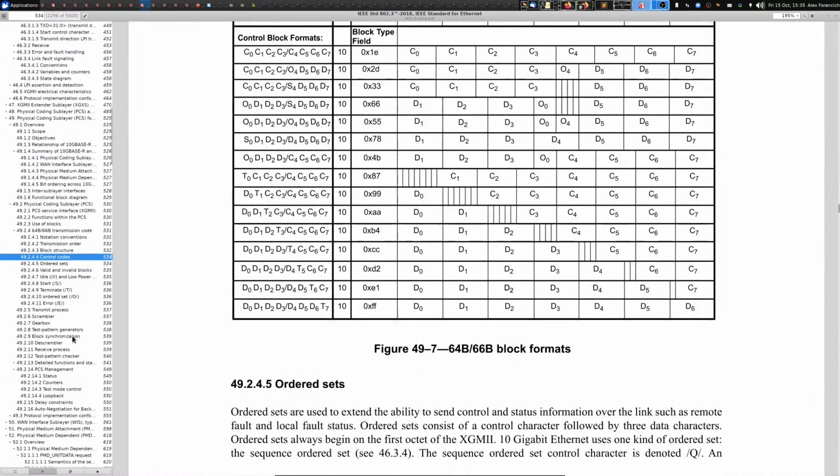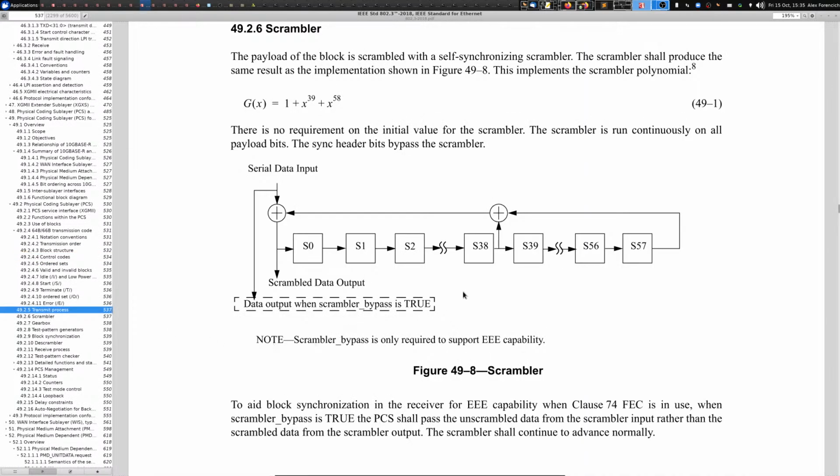6466, on the other hand, uses the scrambler, and it puts statistical bounds on the DC wander. It can't wander more than a certain amount, because you have all of these bits in your LFSR, and you can compute the probability of having a run of ones or zeros longer than a certain length in a certain time period. So by putting statistical bounds on that, that's pretty good. It's not perfect, obviously, but it's pretty good.